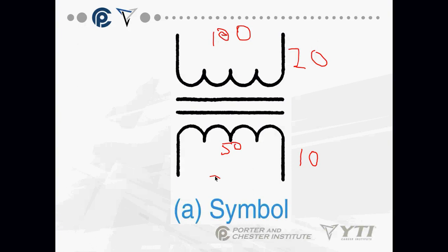Now again, I could do this or the other way around. If I'm putting 200 volts in here, okay, and this is only 50 windings, if I have 100 windings up here, I'm capturing more of that magnetism and I'm going to possibly put 400 volts out. Now the problem that comes up is the current changes.